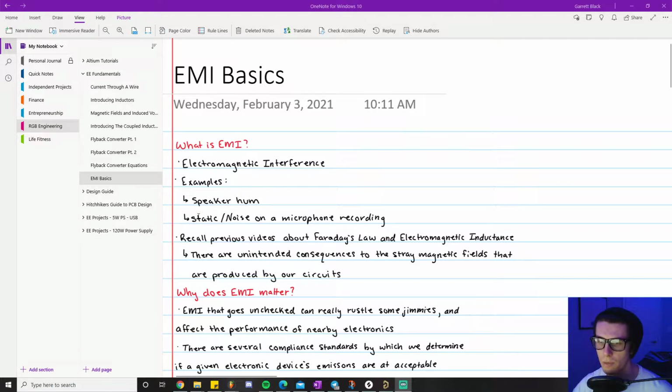The same thing goes for if you've ever recorded your own voice with some type of voice recording software that doesn't have automatic filtering on it. So a good example is Audacity. If you ever record your voice on Audacity, when you hear the first playback, you're like, wow, it's so noisy. Where did that even come from, right? That's from EMI being picked up by not your microphone itself, but the microphone cable is acting like a receiving antenna, much like a radio would, or like your satellite dish antenna.